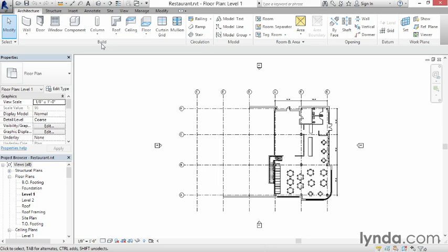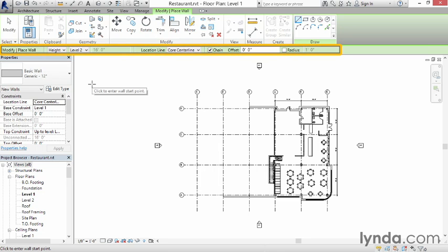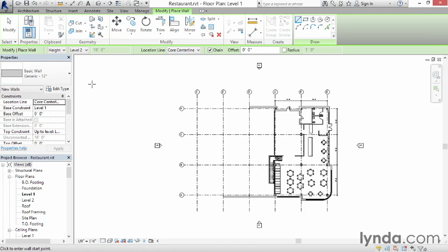And so this is very common in most software like Office or other programs where all the commands are listed on the ribbon. Beneath the ribbon is this little gray bar, which is currently empty. So I'm going to click the Wall tool to show you what that might look like. If I were drawing a wall, you'll see the option bar lights up with a bunch of options specifically for this command. You want to keep your eye on the options bar as you're working because it will change frequently. Each time you run a different command, you'll get a different set of options.